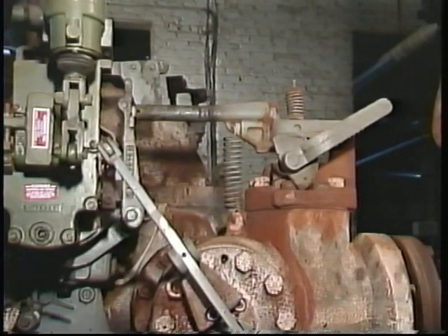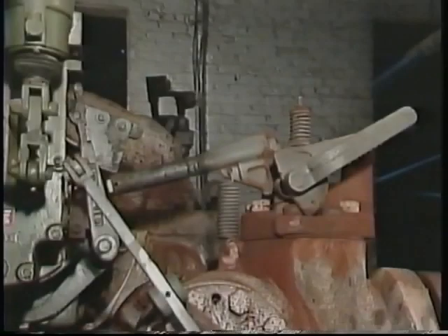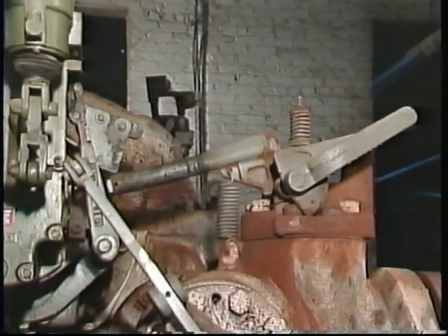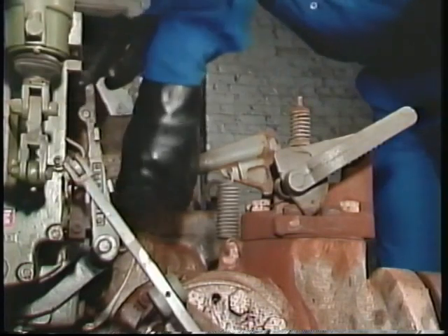Also associated with the overspeed trip mechanism is a hand trip lever that the operator can use to trip the turbine by hand. Manually releasing the lever's latch causes the trip valve in the overspeed trip mechanism to shut and stops the turbine. Whenever the trip has been activated, either automatically or by hand, it must be reset manually before the turbine is put back into operation.